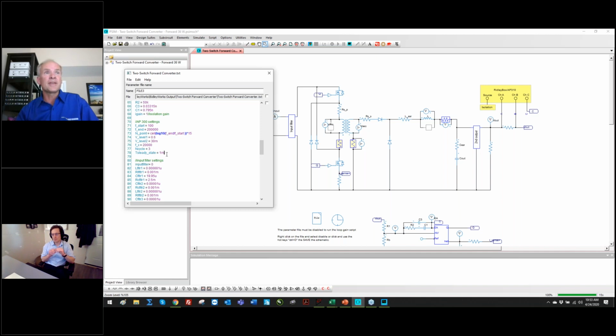And then we have a transient time. When you inject a new signal, you can't just start measuring in the simulator. You have to let 1 millisecond time out, then you run a cycle, then you collect 2 cycles. So this is really intensive work. Let's go sweep down to 10 hertz here.